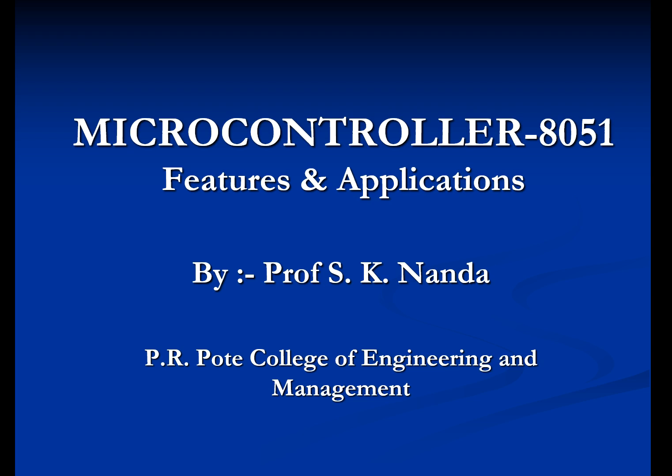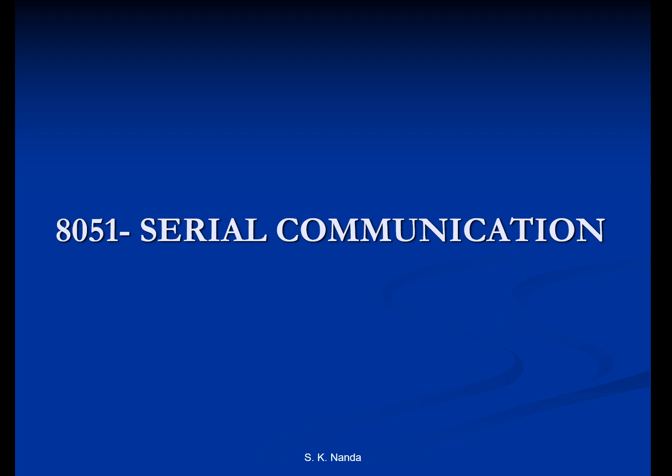Hello dear students, today we are going to see serial communication. Now the 8051 microcontroller is a parallel device that transfers 8 bits of data simultaneously over 8 data lines to parallel IO devices. Parallel data transfer over a long range is very expensive. Hence, serial communication is widely used in long distance communication.